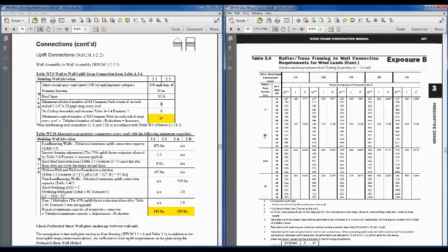And for 16-inch on center rafter and truss spacing or wall spacing, over here under 160, you see that for lateral and shear connections, sorry, hang on, I'm not seeing it. Oh, yeah, the 479. Sorry, the uplift connection is 479 for that 32-foot wall spacing.